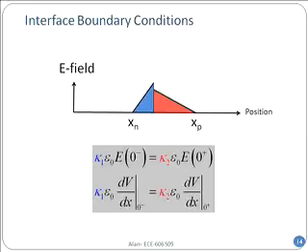Do I remind you one more time that if you have two different materials, then you have this kappa 1 and kappa 2, and the electric field is not continuous, right? Electric field is not continuous. What is continuous? Displacement. D, the displacement, is continuous only if, by the way, and especially in a heterojunction bipolar transistor, you do not have any interfacial charge.